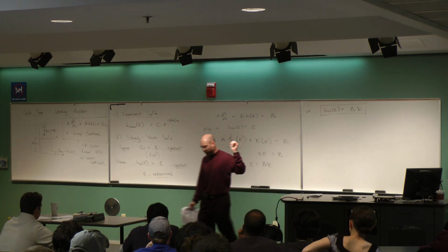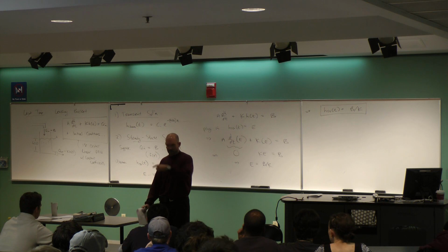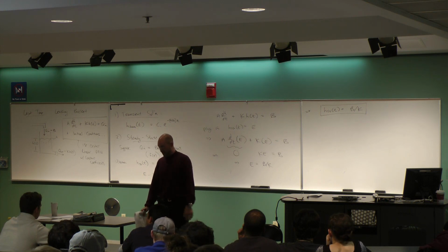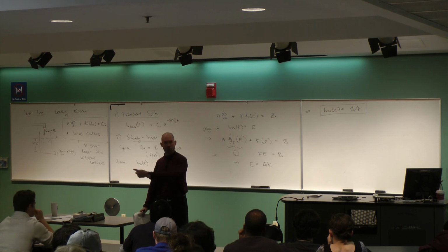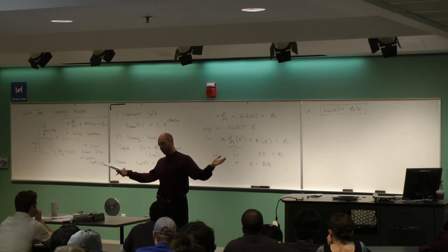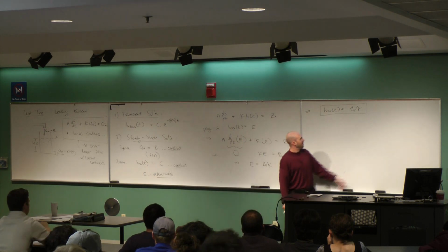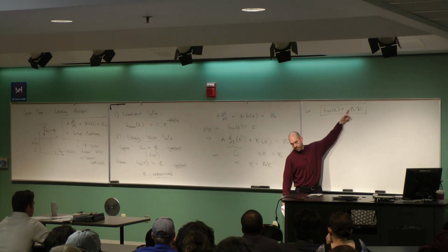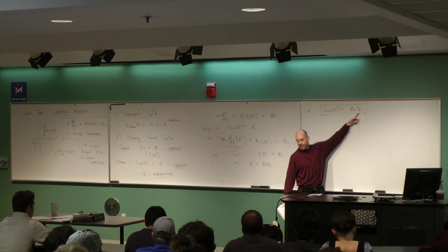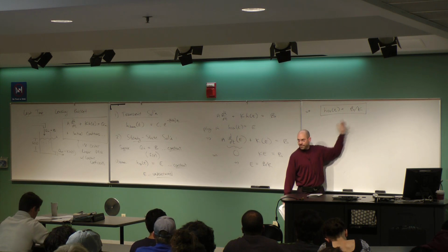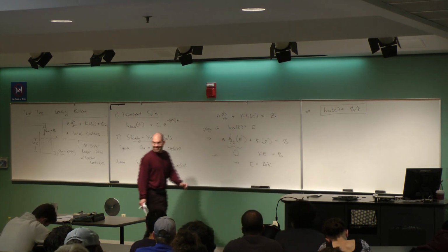So I just said that a steady state solution for this problem, the steady state value of the height, in other words, how high up does this thing go and sit there when the water coming in is at the same rate as the water going out? That's the steady state. What does it depend on? Well, according to this, it depends on how fast the water's coming in. That makes sense. It depends on how big the valve is at the bottom, and whether I got molasses or water. That's the K. These are the things it has to depend on. Sanity check. So it makes some sense, yes? Okay.